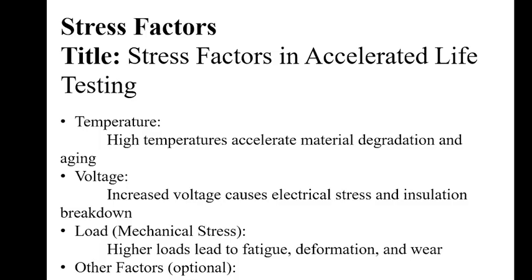In some cases, additional environmental factors such as humidity, vibrations, and pressure are also considered. By systematically increasing these stress factors, you can simulate long-term usage conditions in a much shorter time frame.